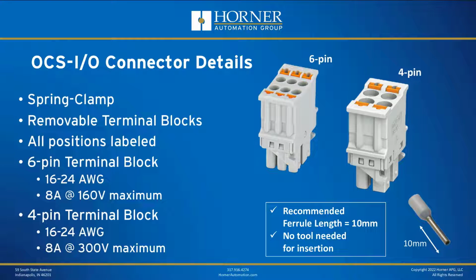One thing you may not have been able to glean from the video, and that is the fact that the IO terminals are all removable. Okay, so they're all removable, they're all labeled, they all support anywhere from 16 to 24 AWG. They're all spring clamp style. And there's a little difference in the current capacity, but for the higher current relay module, we do use slightly larger blocks in terms of the current capacity there.